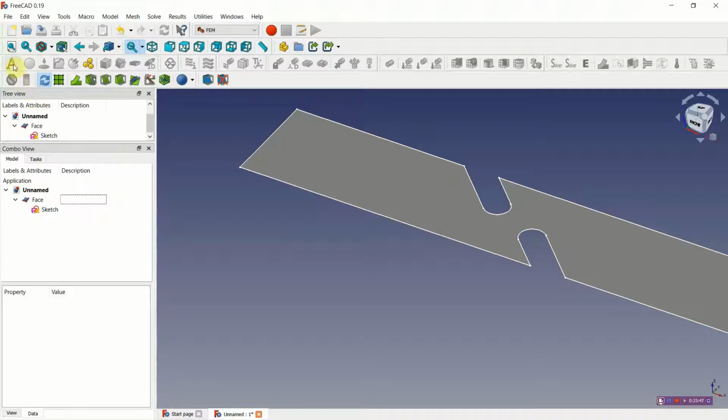The best way to proceed, I should really have started an analysis container. So that comes here. And everything we have now for the mesh, the loads, the boundary conditions will be below this analysis container. So that's created using this symbol here. This is our tool for running the code. We will use that in a few minutes.